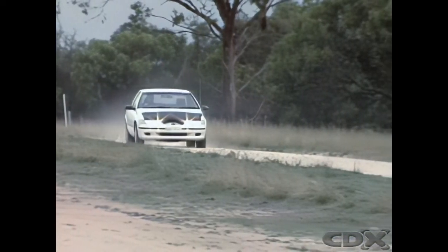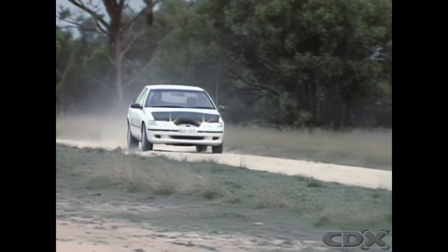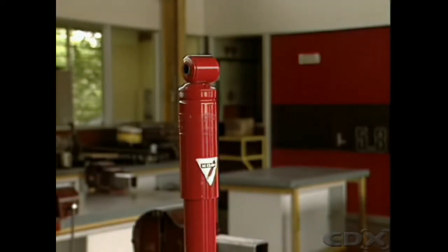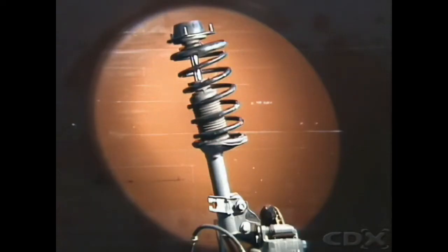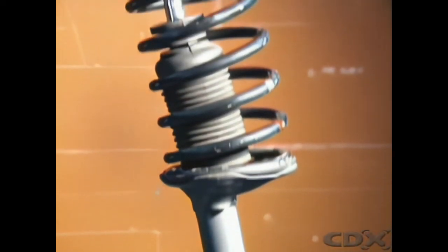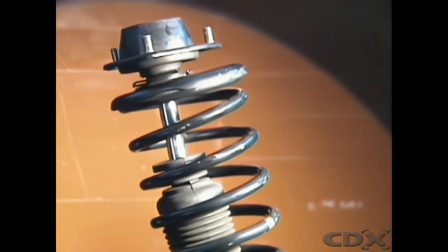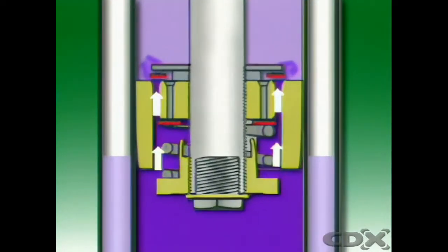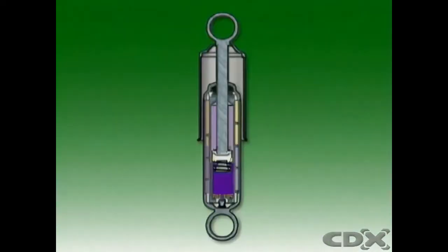The most widely used hydraulic shock absorber is the direct-acting telescopic type. It can be fitted as a self-contained unit, or combined with a suspension strut. The strut type uses the same principle of operation, but it is considerably larger. The hydraulic shock absorber provides its dampening action by transferring oil under pressure through valves which restrict the oil flow.